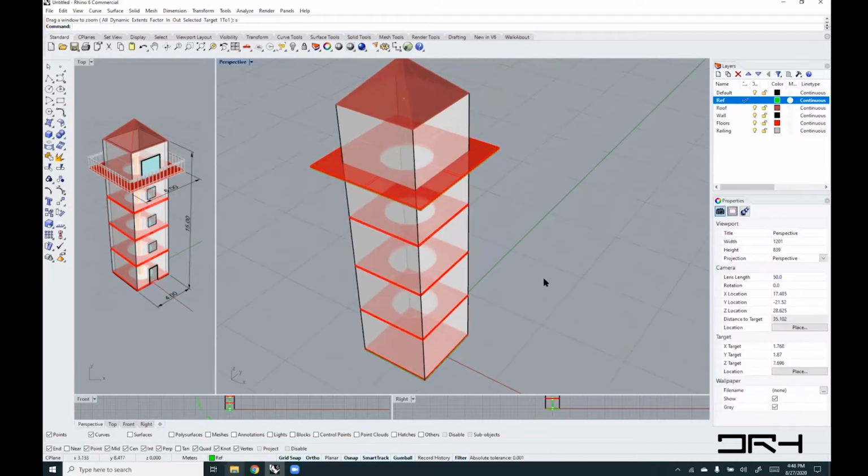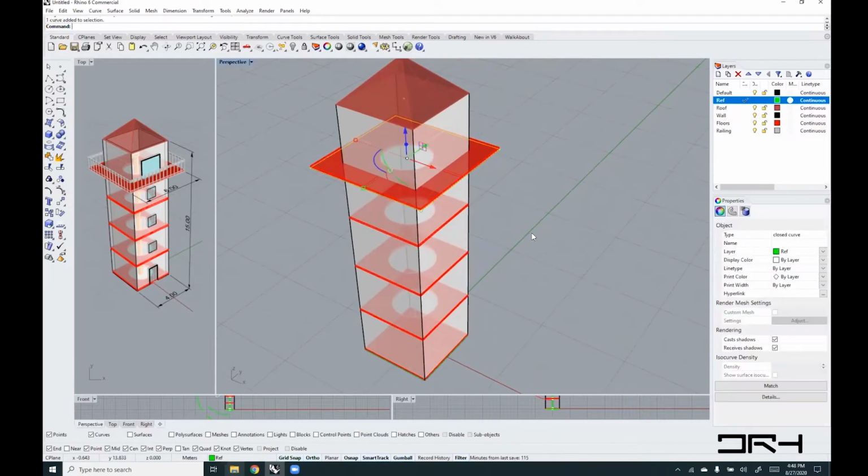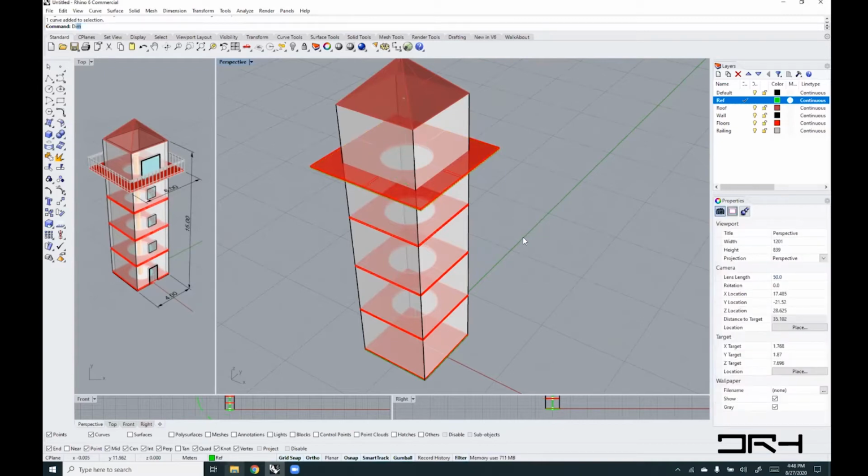So now let's do it again. I will select my curve. I first call the Divide command, and it asks me to select my curve. I do. And then the seam, just keep it where it is. The number of segments, we said we will do 40. And I have all my points now.